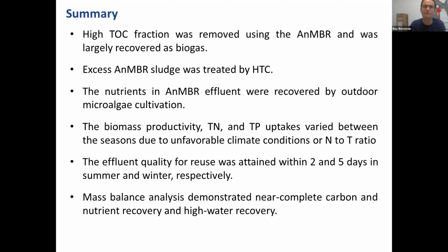So altogether, we can say that we were able to establish a very nice scheme for really near zero waste disposal. We had a very high TOC fraction removed using the anaerobic AnMBR. We could recover carbon using the hydrothermal carbonization. Here we need to investigate what we can further do with that. Most of the nutrients were recovered, especially the TP uptakes were very, very high.